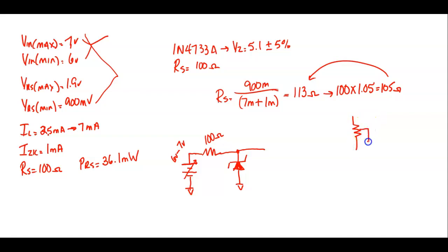We can come over here and do this, and now this is a pot to act like a rheostat. Or you could do this, and you take your output off there. Now, what's the problem with using this is you've got an antenna sticking out in the air, right? You understand that? And it becomes very noisy. So this is the preferred method right here.